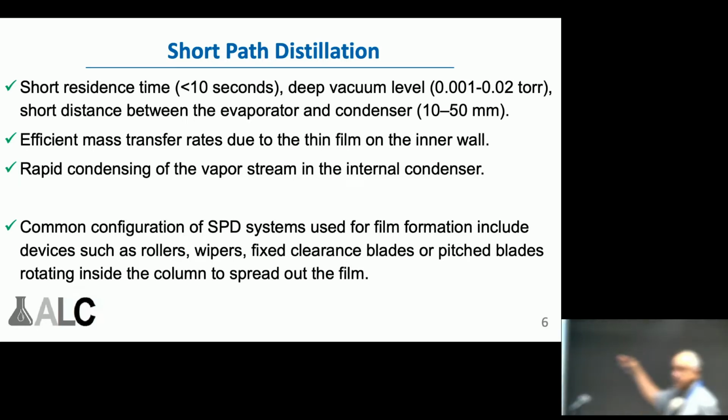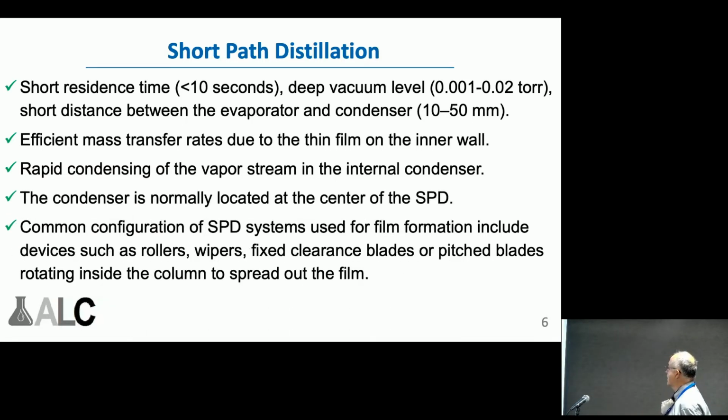Usually, the molecular distillation unit will have these mechanically agitated systems, whether it's for processing lecithin, whatever it is, scrape surface heat exchangers, and when you apply an internal condenser to that you have the short path distillation effect, basically. So, this condenser is usually in the center of the body of the system.